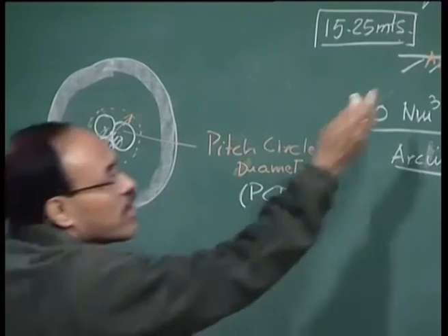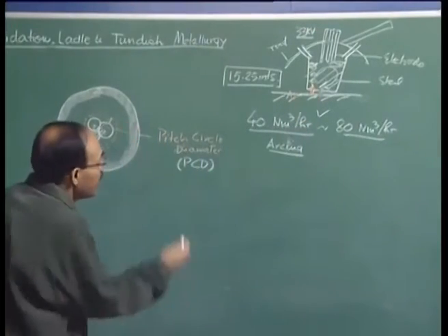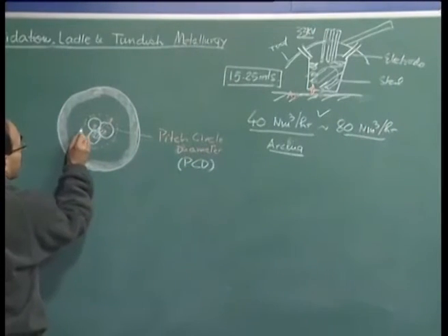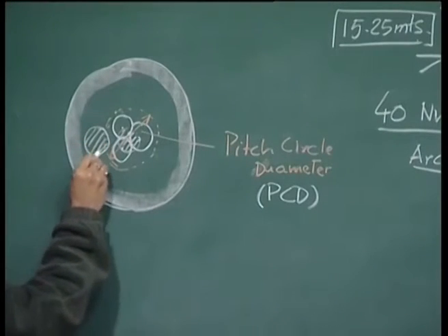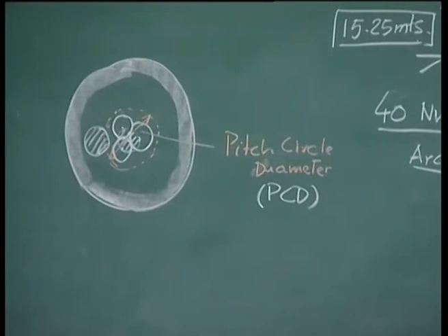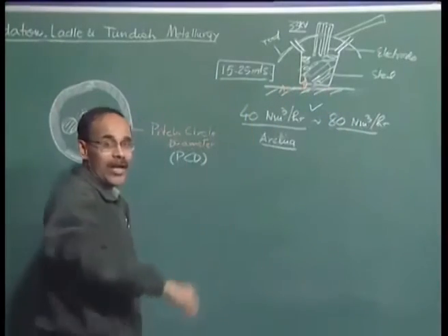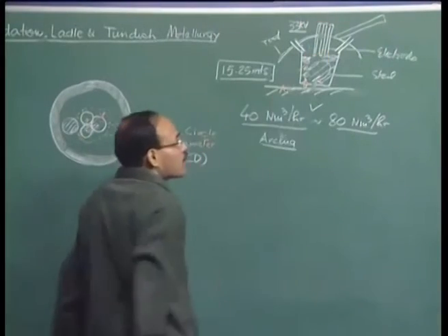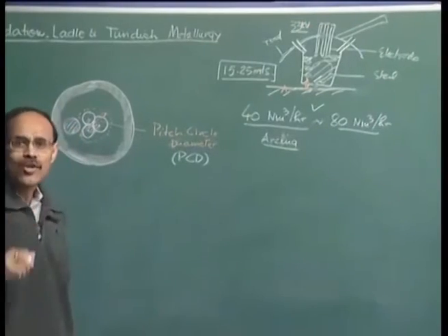On the other hand, if the porous plug is located a little bit away towards the wall itself, then the area in which the plume is going to be surfacing will be represented by this hashed area. So, by displacing the porous plug towards the wall, it is possible to prevent direct contact of the surfacing plume with the electrode.